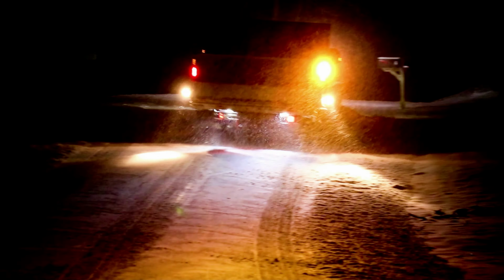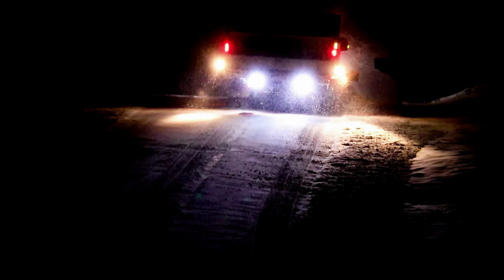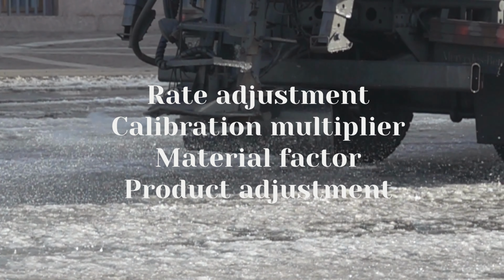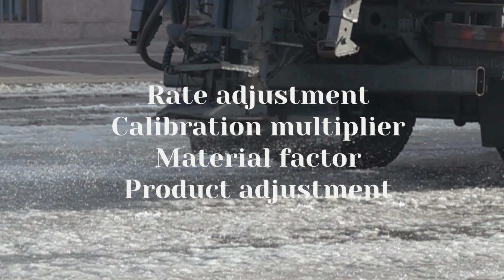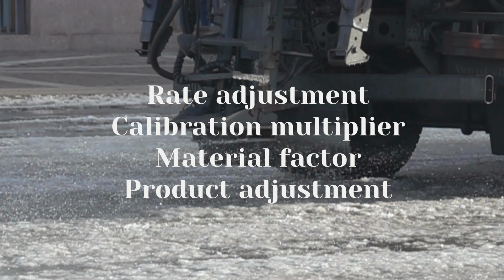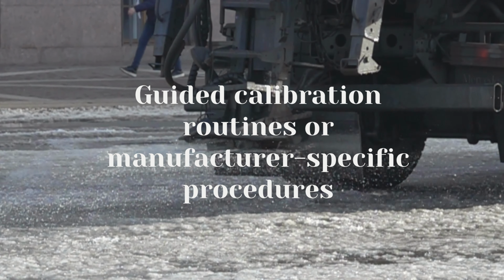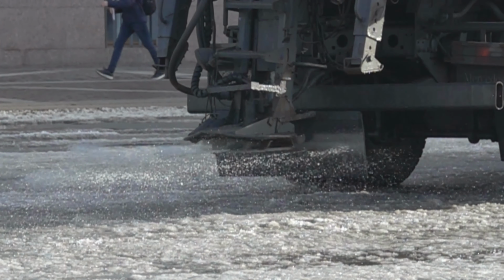Unlike manual spreaders, where operators can adjust output primarily through truck speed, conveyor speed, or gate height, some computerized ground speed controlled systems include adjustment settings that can help fine-tune material output based on measured performance. Depending upon the controller system, adjustment terminology may vary. Some systems may use terms such as rate adjustment, calibration multiplier, material factor, or product adjustment. Other systems may use guided calibration routines or manufacturer-specific procedures instead of direct factor entry.